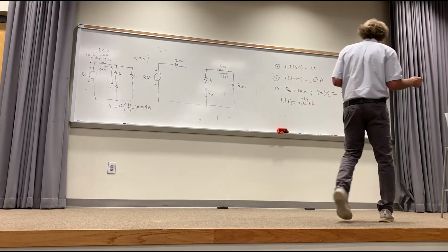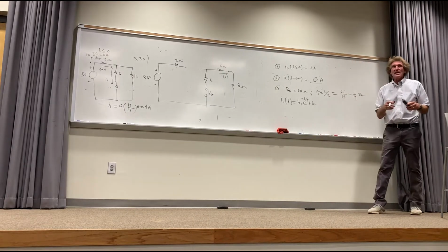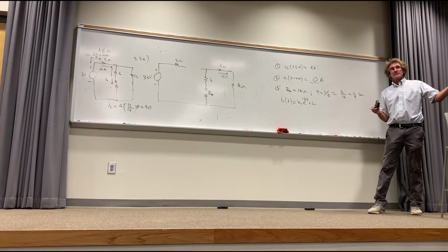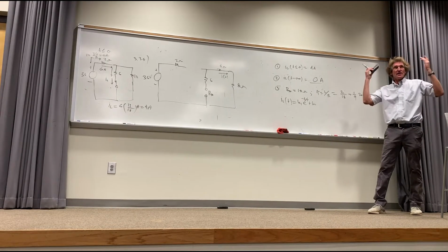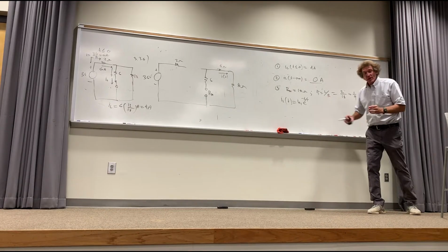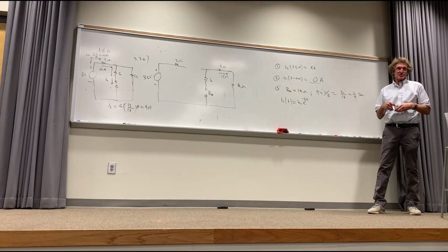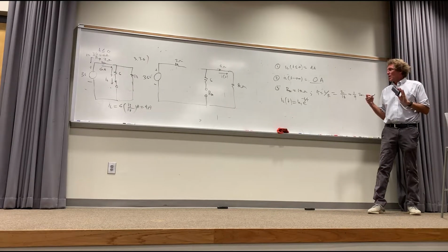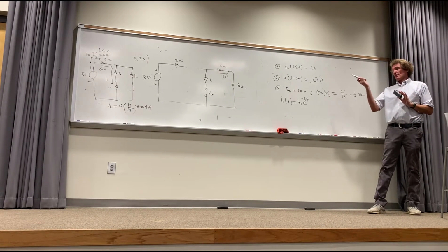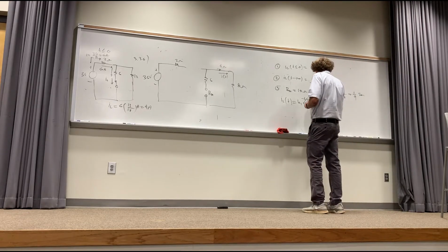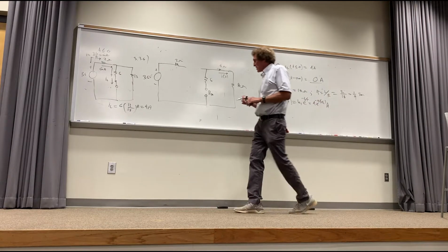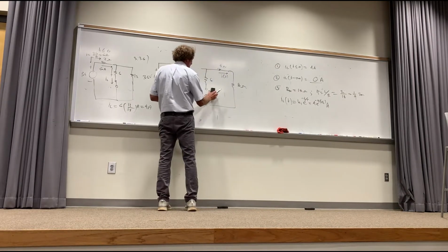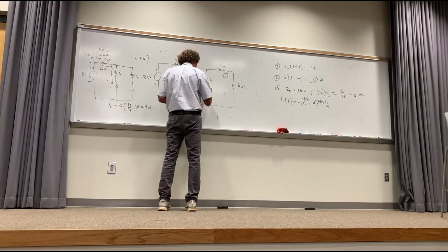All right, now, just look at this. What is K2? Well, it's the current at what? T equal infinity. What is the current at t equal infinity? 0. I'm just trying to get you to respond so I know you're there and it'll help you remember, trust me. What's K1 gotta be? 4, yeah. This is just 4 e to the minus t over tau, where tau is 1/9 of a second, in amps. Now that's the current that flows. This is for t greater than 0. This is the current, literally, we know this current.